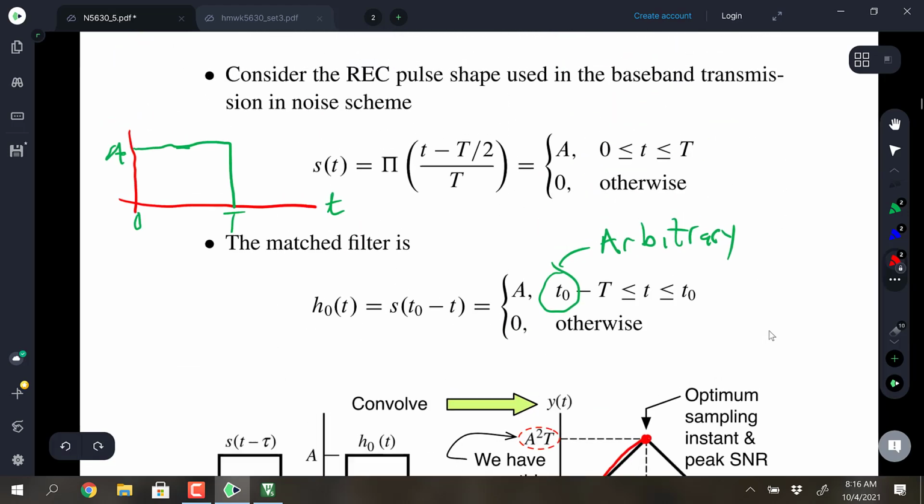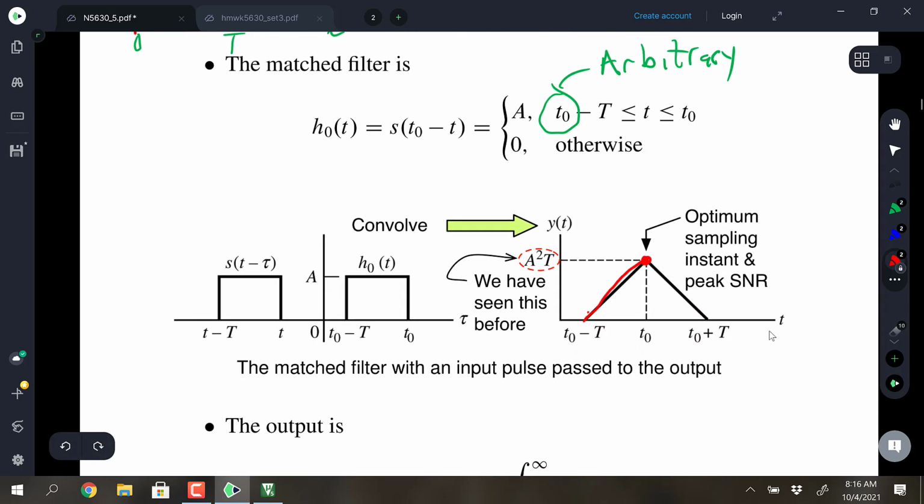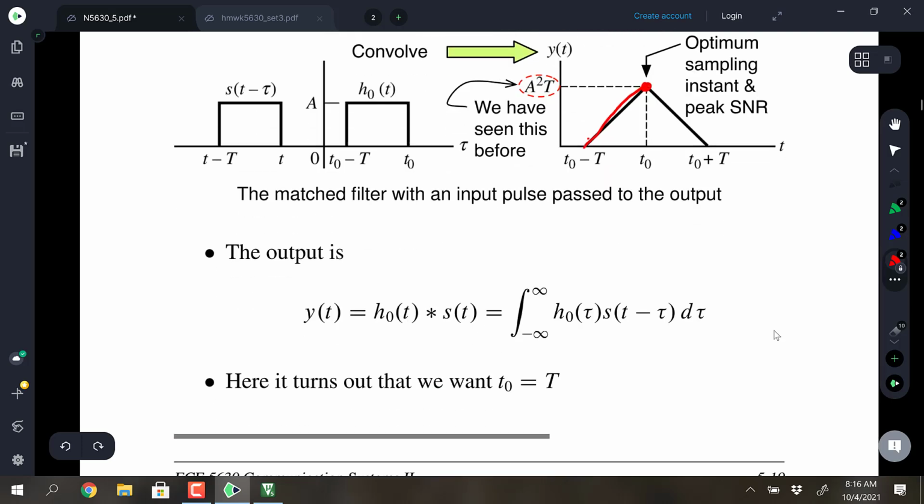The only thing that maybe seems funky about this is, what about S2? There's no S1 or S2 in this case, but if it helps, you can just simply say we're going to send a pulse when we want to send a 1, and we're going to send nothing when we want to send a 0. That would be a very simple form of pulse amplitude modulation, or in optical communications, it would be called on-off keying. So we're just looking for the presence of something, or not the presence of something.